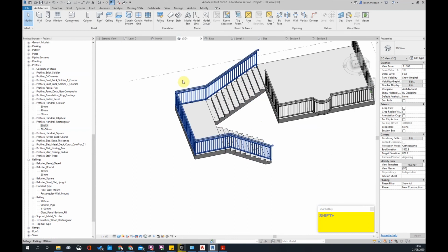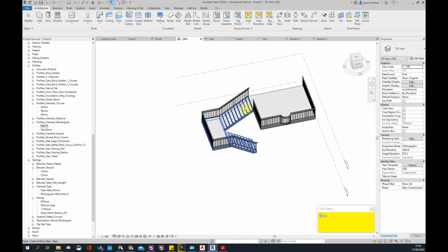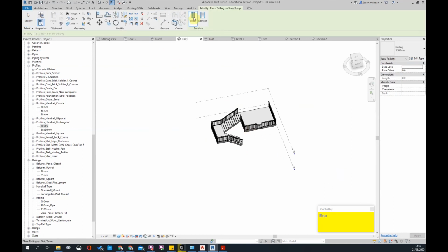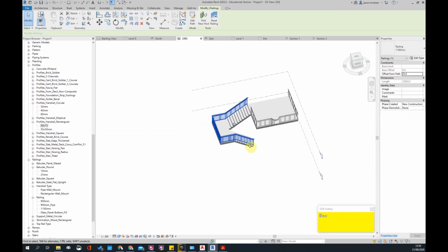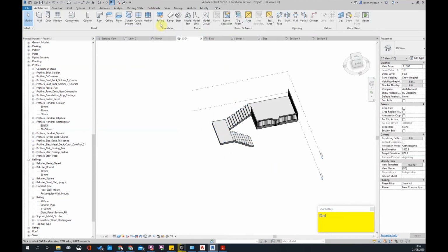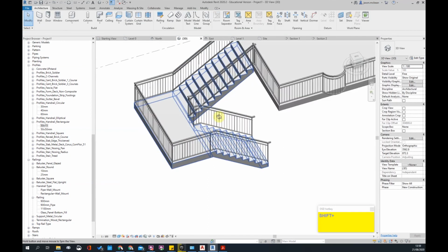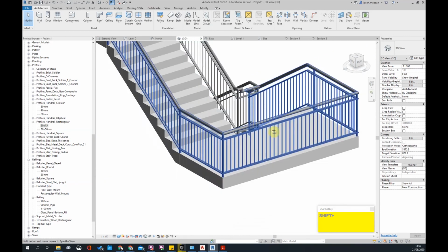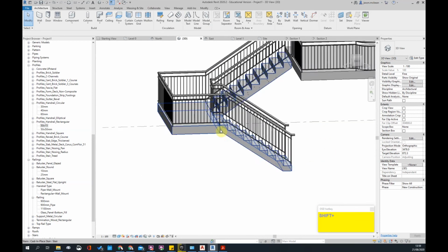So railing. I'm going to grab one more, place railing and stair. So I'm going to select the inside again. Railing, place and stair, stringers. I want it on a tread. Why is it not selecting the stair? Let's get rid of this. Railings. There we go. So that's what the gooseneck does. When it comes to a difficult situation, it goosenecks up. It just makes a neater terminal. So that's why I've done that. So generally, that's for what you got.